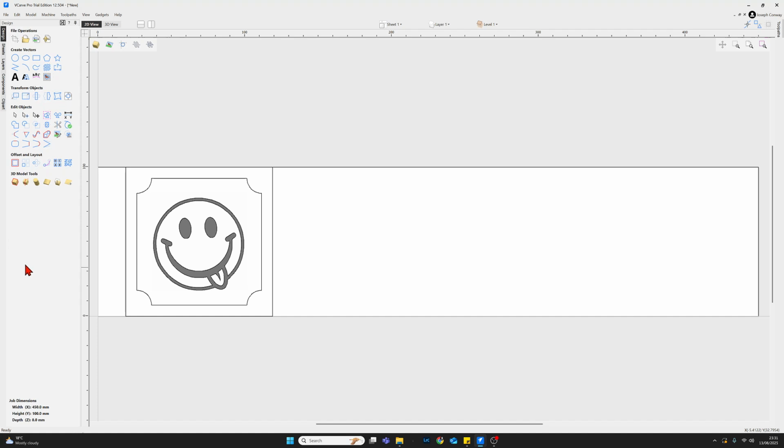There we go. So before we move on, let's go back up now and just have a look at what our layers are doing. And we see now that we've got an additional layer, which is the bitmap layer. Now, if I select it, you'll see it's now in bold, which means that is the focused layer. If I click on the radio button to hide it, you'll see here, this is the actual vector file that we will be working with. So if I select that again, what we're seeing at the moment is we're still seeing the JPEG image, but that has no meaning to us, and hopefully we can get rid of that.